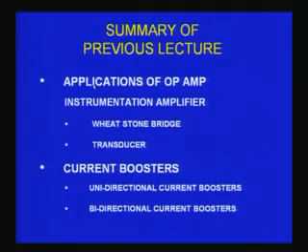You might recall, as you see on the screen, we discussed the applications of operational amplifiers, especially the instrumentation amplifier configuration, how it can be used for amplifying the signal from a Wheatstone bridge, and how in a Wheatstone bridge you can have a transducer or a resistance sensor connected in the form of a bridge, used along with the instrumentation amplifier, so that you will be able to measure different parameters like the strain or the temperature, etc.